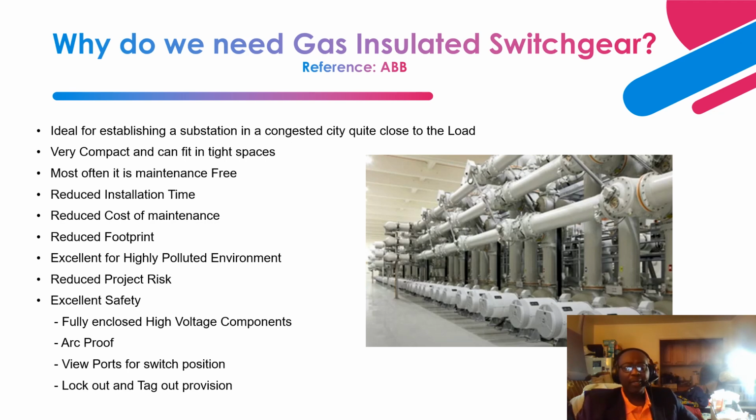Next, lockout tagout, right? If you need to perform maintenance on it, or if there is any problem with it and you need to perform isolation of the GIS, there are dedicated lockout tagout provisions provided by the OEM for you to be able to isolate these GIS components.